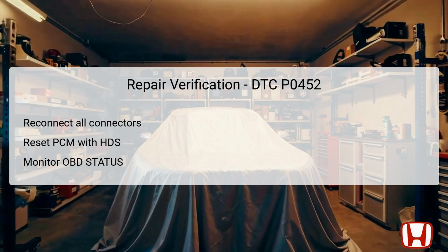In this repair verification step, it is important to reconnect all the components and connectors that were previously disconnected during the troubleshooting process. Subsequently, reset the PCM using the HDS to ensure that all previous fault codes are cleared and that the control module is operating under the latest parameters.